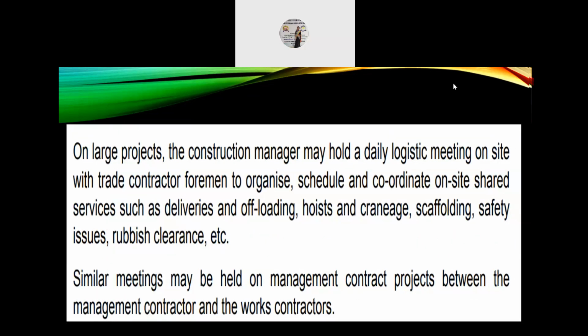On large projects, the construction manager may hold a daily logistic meeting on site with trade contractor foremen to organize, schedule, and coordinate on-site shared services such as deliveries and offloading, hoist and craneage, scaffolding, safety issues, rubbish clearance, etc. Similar meetings may be held on management contract projects between the management contractor and the works contractor.